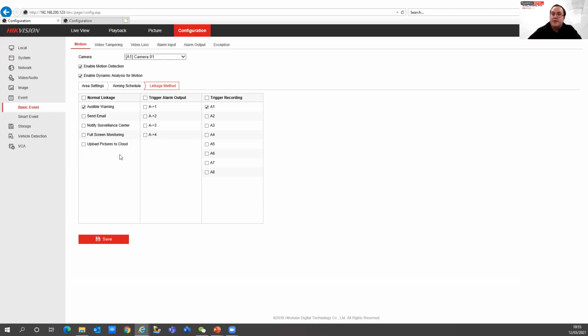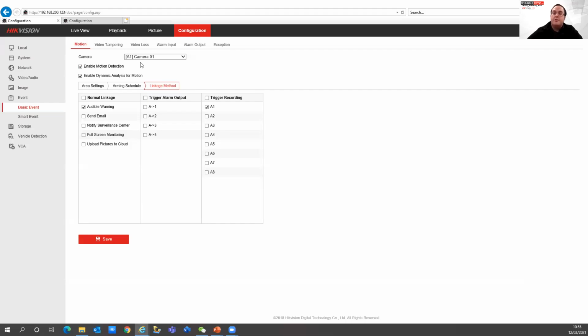With third-party services such as OneDrive and Google Drive, they're not designed to be having CCTV images uploading regularly, and there's also additional costs to that as well. So generally we do recommend either using VideoLoft or the new Hikvision solution with the cloud box, using Hik-Pro Connect for cloud backups, which will only be done on event storage for the actual system. So if an event's triggered, that can be uploaded to your cloud system there as well.